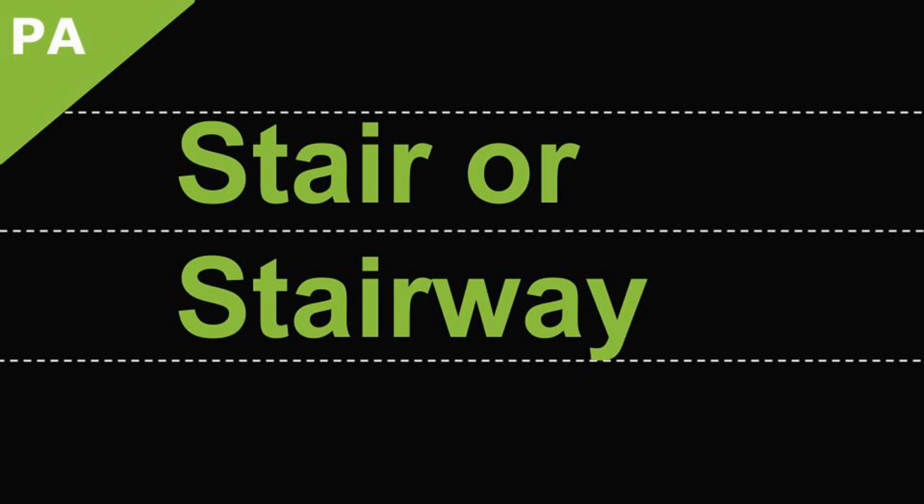Stair or stairway. A stair provides a change in elevation with one or more risers. A stairway is one or more flights of stairs with landings necessary to connect from one level to another. These requirements are located in Chapter 10, Means of Egress, Section 1011, Stairways.